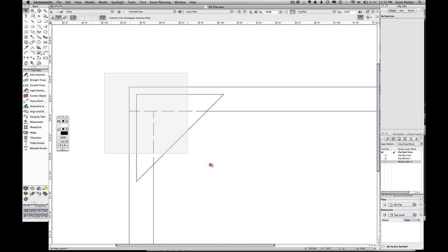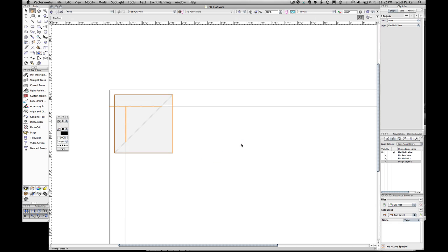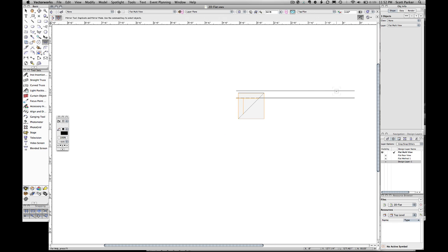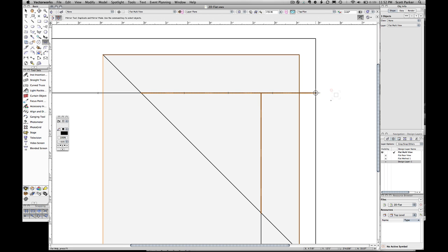Now I'm going to take all of these objects and mirror them to the other side. It saves a bunch of drawing if we have it pre-planned. So I'm going to hit Mirror and find the center of this board. And there's the center there. It snaps to center. I'm going to pull this straight down and click. And so there's the other side. Now the dashed lines did copy. It's just that the solid lines are blocking that.